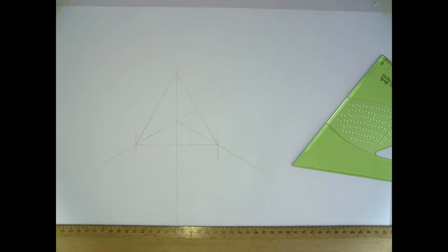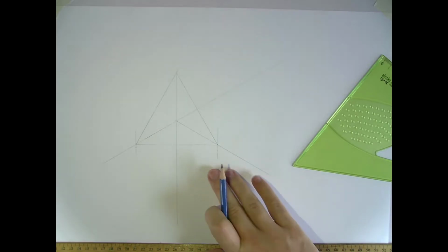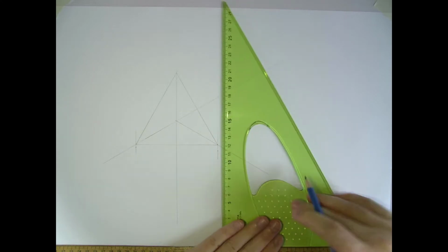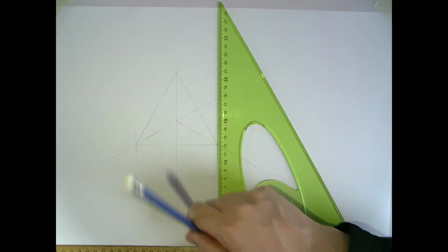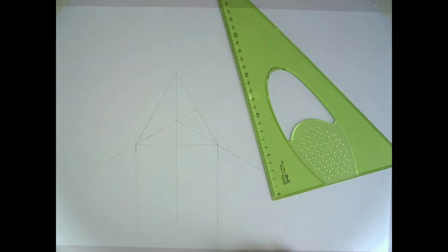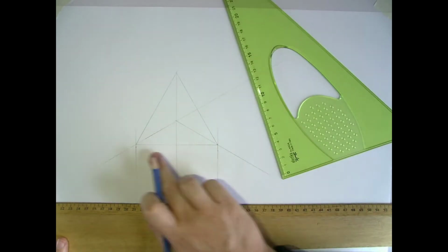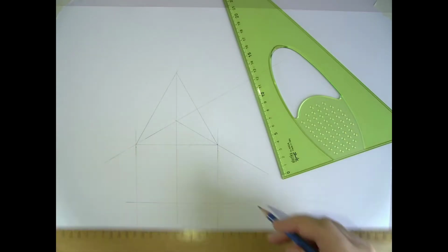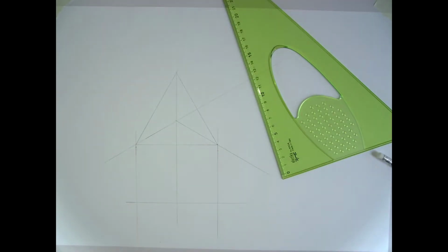In the next part of this, we now need to draw the elevation and plan positioned as shown. So the plan is going to go down here directly below it. So let's do that first. So lines projected down. Pick a horizontal line down here somewhere. It's drawn parallel to this one. And in that, we're going to draw a semicircle.